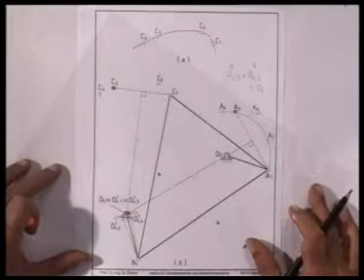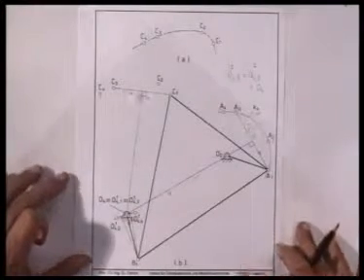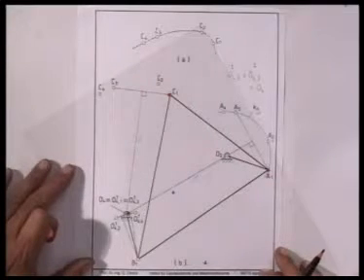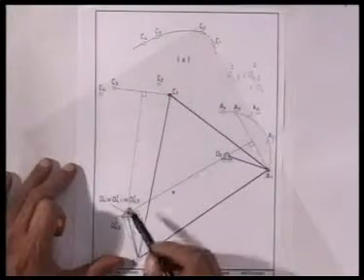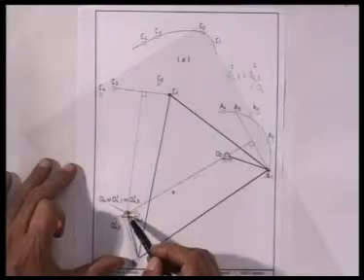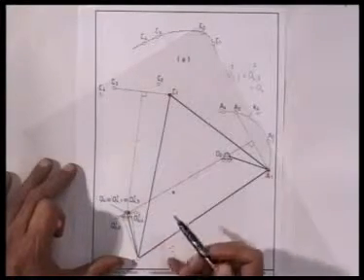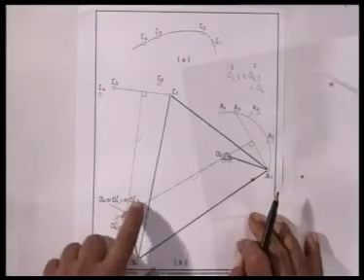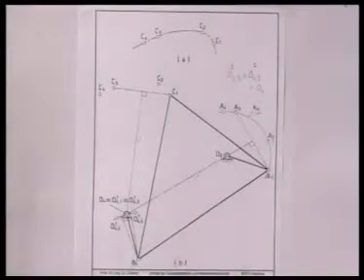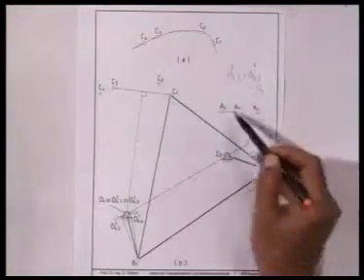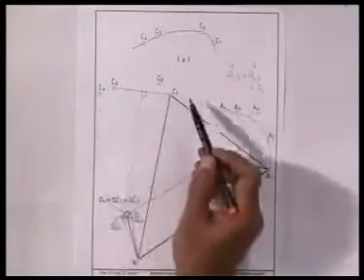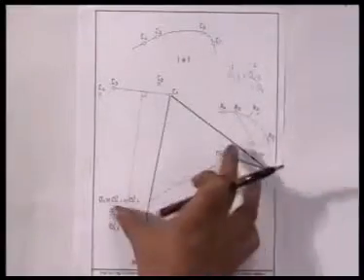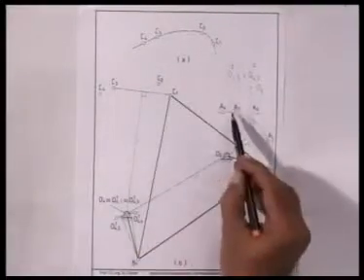If I invert it on the first position, that is A3 coincides with A1 and C3 coincides with C1, as we see the point O4 does not move. So this is also O4, 3, 1. It is the same point, O4 is O4, 3, 1. This is obvious because O4 has been located on the perpendicular bisector A1, A3 and C1, C3. So O4, A1, C1, this triangle moves as a rigid triangle from the first to the third configuration.